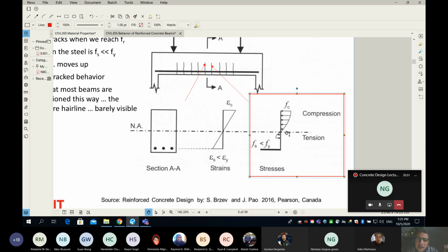And we agree that everything above the neutral axis is in compression and everything below the neutral axis is in tension. So you can see there is one thing above the neutral axis, which is concrete. However, at the bottom of my neutral axis, there are two things. One is the rebar in red here. So those are the rebar. And also there is some concrete in tension.